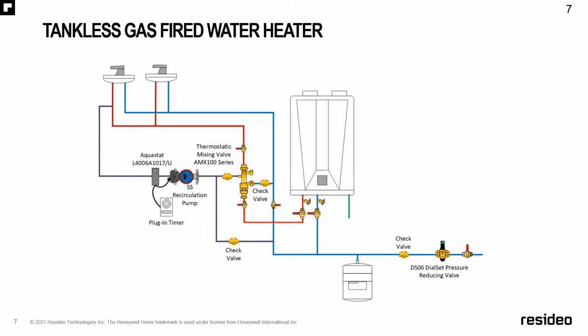And you also, on this illustration, see a mixing valve. Now, some people might say, well, why would I have a mixing valve on a tankless water heater? Because I can set the output temperature to whatever I need. Well, you can actually increase that target temperature to 160 degrees, and mix it back down to your operation temperature, which is like 120, 125, which you have codes for. And you actually increase the output.